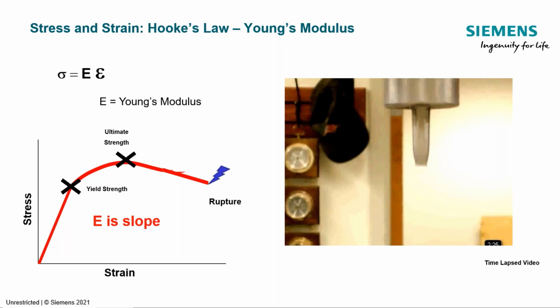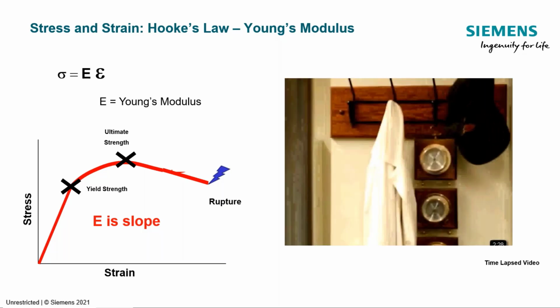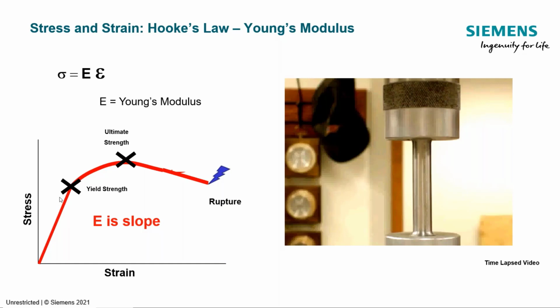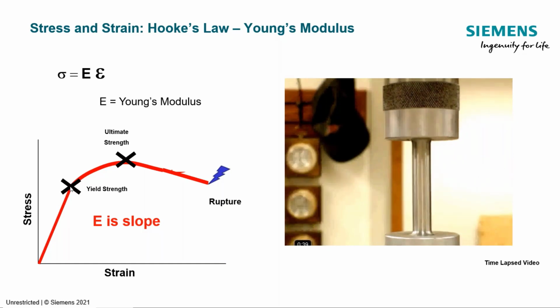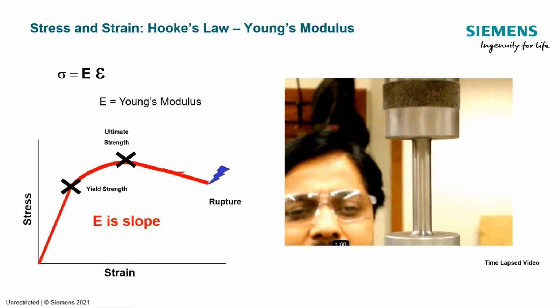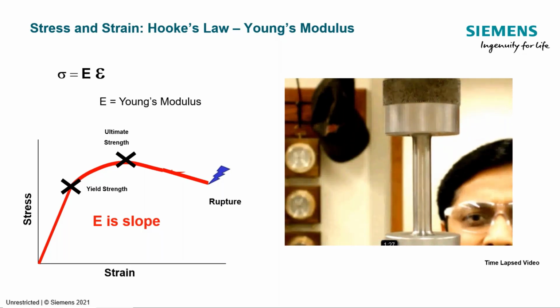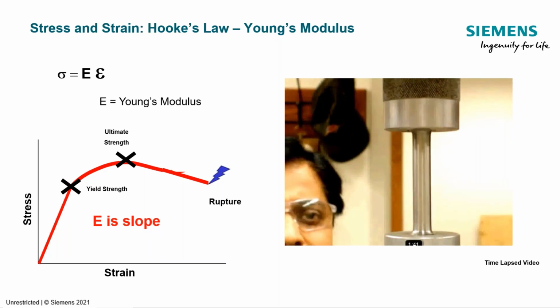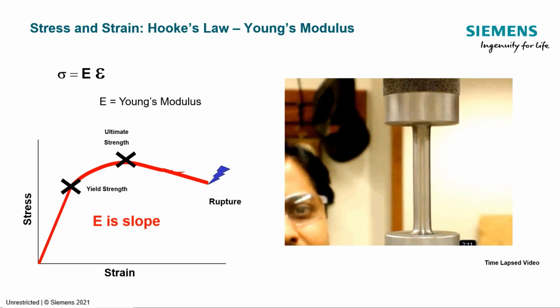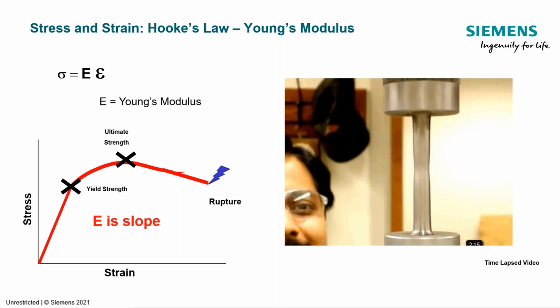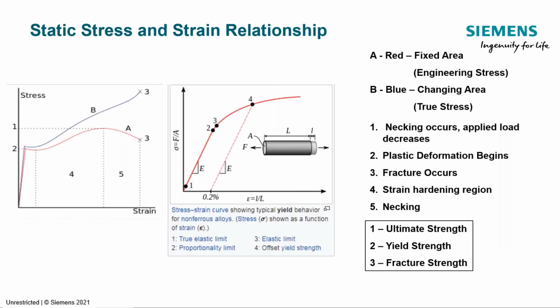Well, in every fatigue analysis, we need the ultimate strength. They don't always ask for the yield point, the yield strength, and we'll see there's several ways to measure that, but that's an example of where we start to go from elastic to plastic relationship. If it's a linear relationship, stress to strain, we're in the elastic region. If it's a non-linear relationship, then we're in the plastic region. However, there are a lot of ways to define this point, and you'll see they can be very different. So we're going to try to give some insight into these points.